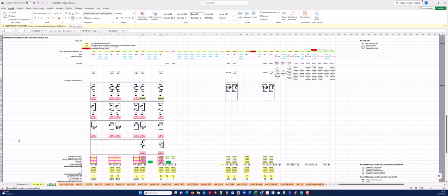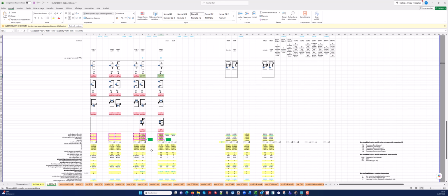Finally, we have to select end corrections for the stage 1 inlet and stage 1 outlet as highlighted in green here. For example, we can select for both a termination connected coaxial model here and here.